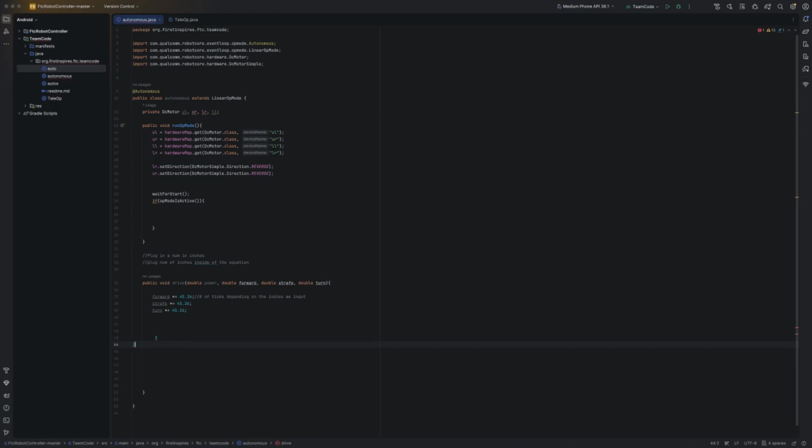Let's say I plug in 3, but because I didn't reset the encoders, the computer detects that it's currently at position 3. So telling it to move to 3 is like sitting on my chair and telling myself, sit at the chair. I'm already sitting in the chair, I don't need to move. So the robot isn't going to move.